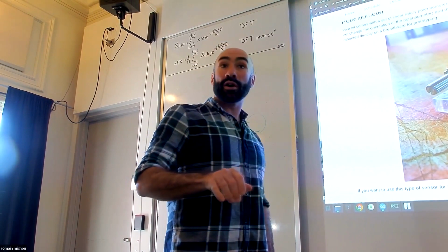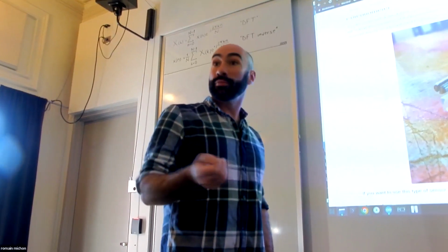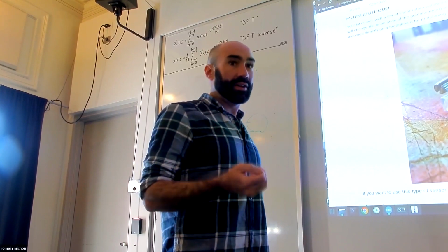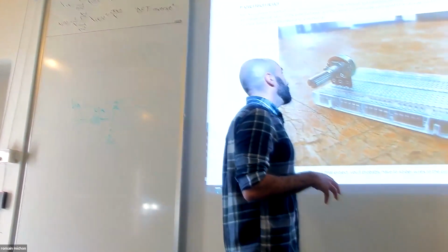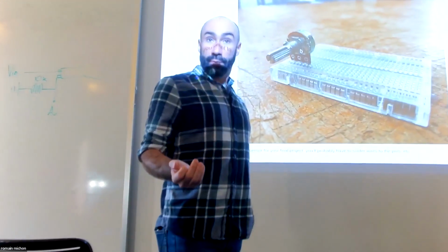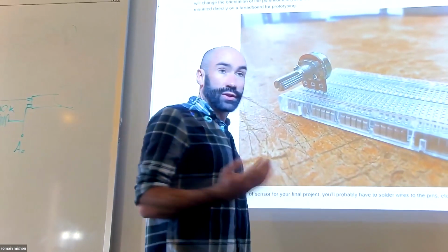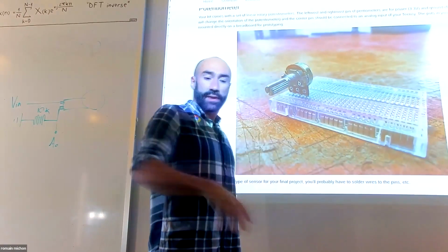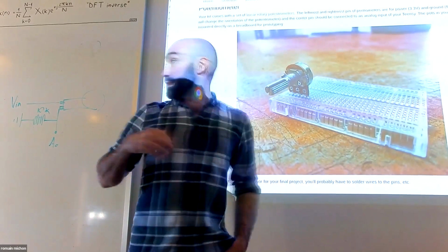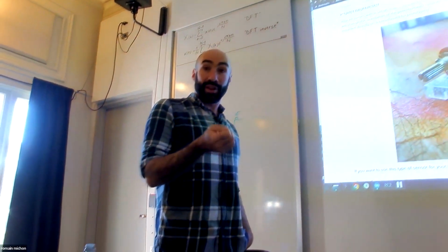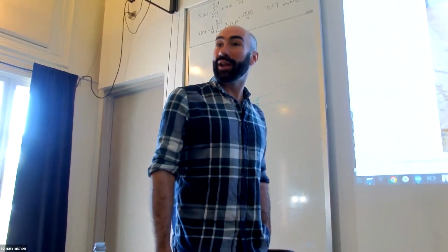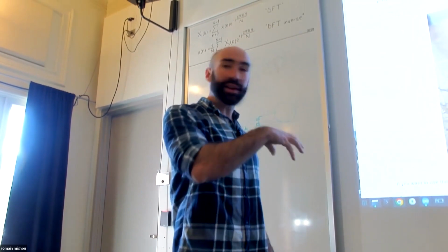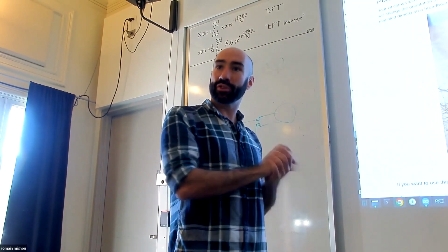Logarithmic potentiometers are typically used to control the volume of a sound, for example, in an analog circuit. And it would be really annoying for you if you were buying logarithmic potentiometers, because you could make the adjustment on the software side, but because the ADCs that we're using are only 10 bits, you don't have a lot of precision, and so it would not really work that well in the end. So if you want to buy new potentiometers, you buy linear potentiometers.